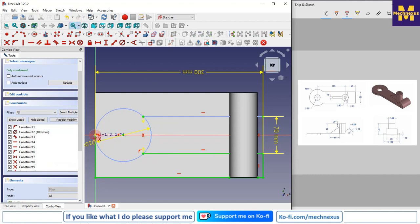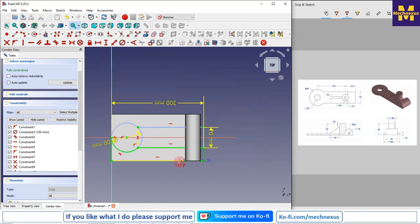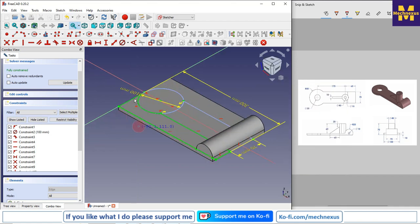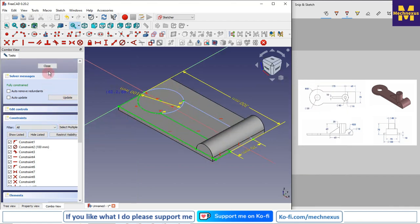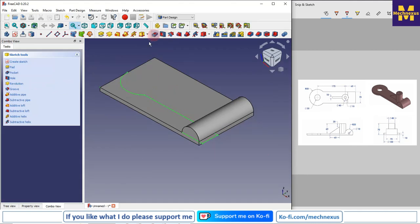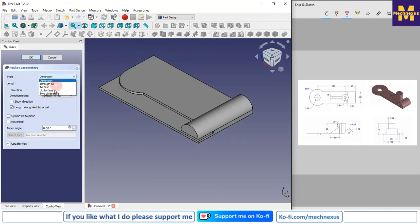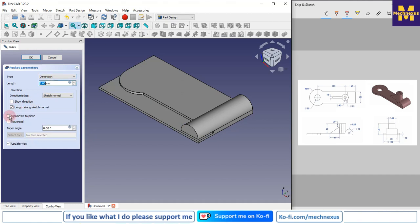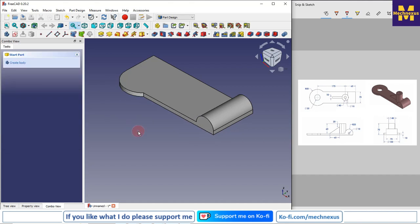And now select the 3-point arc. So here is our closed profile, and now I will switch to the isometric view, and I will close it, and I will go with the cut, and I will say through all, or I will say the dimension, and I will say symmetric to the plane, and I will give a rough 50 mm, so that the complete material is removed from top and bottom.